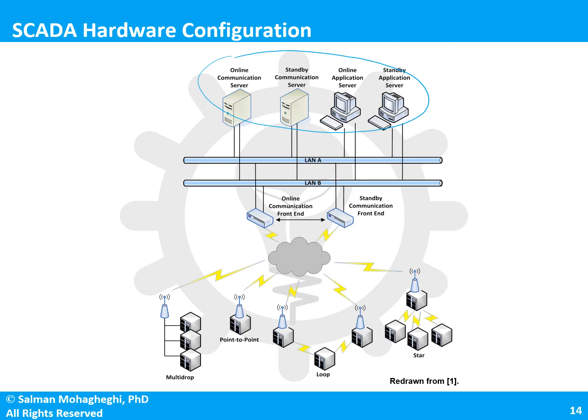As far as communication between the RTUs and the rest of the system are concerned, you could have high reliability designs. Consider this situation. If you have a point-to-point connection, if there's anything wrong with that particular connection, you're going to lose that RTU.